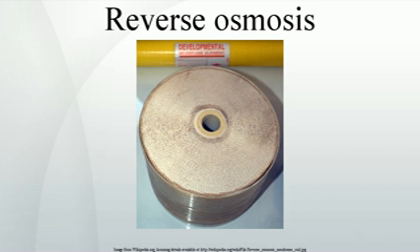Ordinary tap water can contain excessive chlorine, chloramines, copper, nitrates, nitrites, phosphates, silicates, or many other chemicals detrimental to the sensitive organisms in a reef environment. Contaminants such as nitrogen compounds and phosphates can lead to excessive and unwanted algae growth. An effective combination of both reverse osmosis and deionization is the most popular among reef aquarium keepers, and is preferred above other water purification processes due to the low cost of ownership and minimal operating costs. Where chlorine and chloramines are found in the water, carbon filtration is needed before the membrane, as the common residential membrane used by reef keepers does not cope with these compounds.